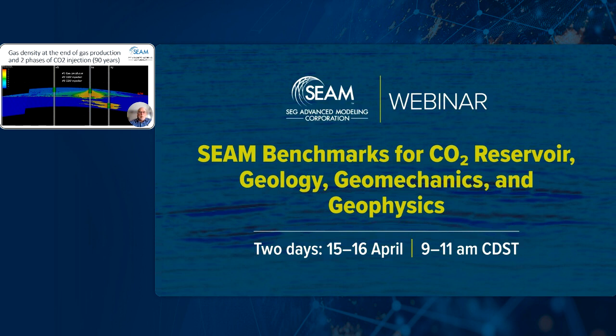This is the reservoir simulation gas saturation for the end result after having depleted the gas reservoir here. Then we've got injection in the lower section with well number 2 and CO2, and then injection here in the upper zone. And this is the gas density at the end of gas production and the 2 phases of CO2 injection.